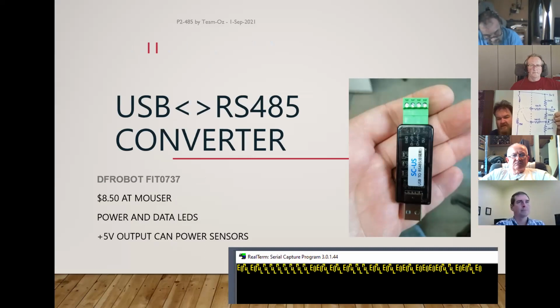The FETs inside the P2 have strong enough drive to be able to send RS-485 level signals out to interface to industrial devices. And so we're just working our way through a number of devices to communicate. Last week, we talked to one of these Advantech Atom industrial modules, and this week I just want to talk about an industrial RS-485 temperature transmitter,